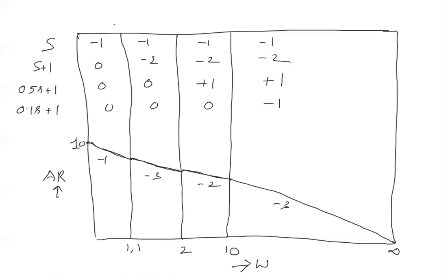See, Bode plots, I think we have done. So basically we'll identify the corner frequencies: before the corner frequency one slope, after the corner frequency another slope. What is meant by corner frequencies? See, the frequency at which the graph changes the slope is the corner frequency.